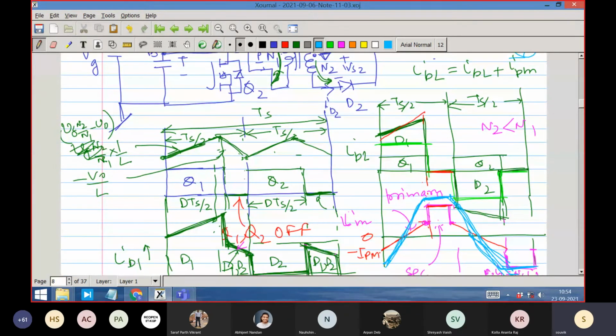It is the basics of the transformer, right? Only thing is that the transformer is very versatile. It may give the magnetizing burden to the secondary. In the first year, second year, you always understood that there was no switch, and that it will always flow from the primary. Here that constraint is not there. Sometimes it takes the secondary side as the convenient one, because on the primary side you said I won't allow any current, I have turned off both the switches. So you are understanding the transformer much better because there are some switches. You are fully exploring all the possibilities that are there in a transformer.